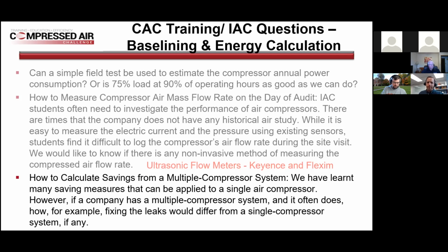When we talk about baselining for fixing leaks in the Compressed Air Challenge training, we'll talk about using load unload compressors and doing a stopwatch on a non-production time to see what the leak load in the plant is, to take your amount loaded divided by the total time, and that'll give you the percentage that you're leaking. If you have multiple systems, I always tell them to lock those compressors in, and just run on the one.